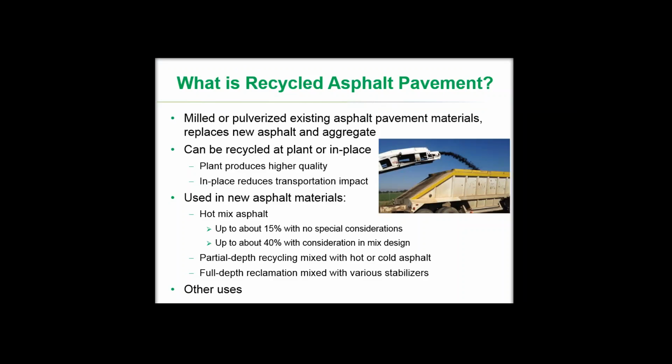What is RAP, recycled asphalt pavement? RAP is milled or pulverized existing asphalt materials, and we use those for a variety of purposes. What we call the highest use, and we'll talk about that in just a minute, is to recycle these back into new asphalt mixes, which can be done either at the plant or in place.